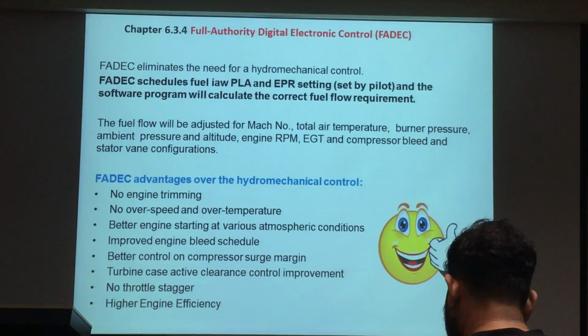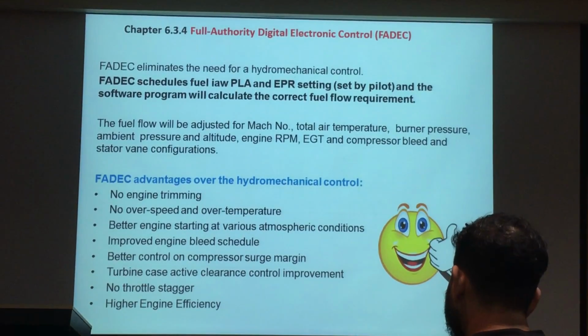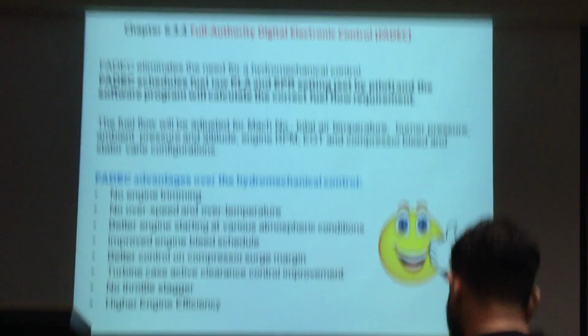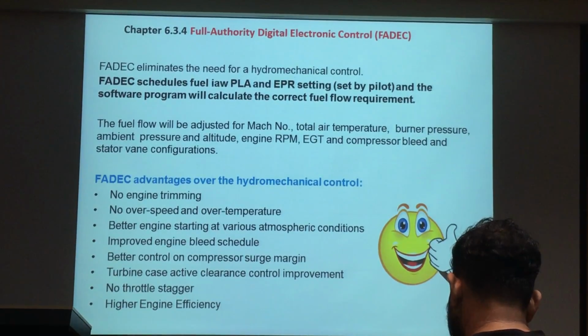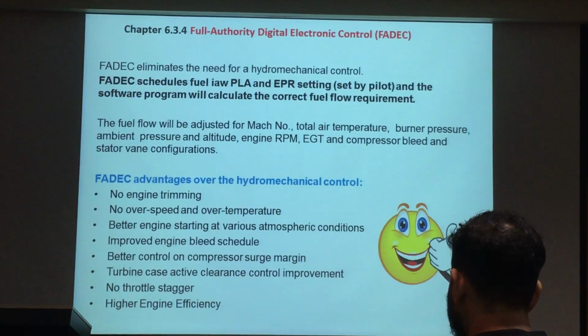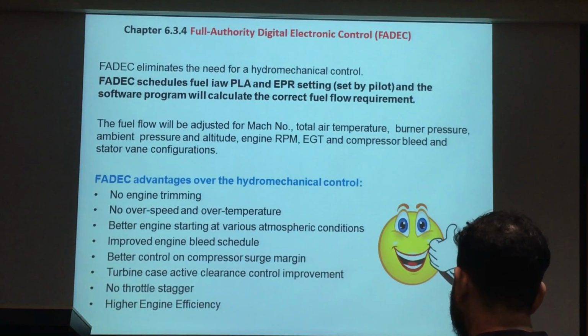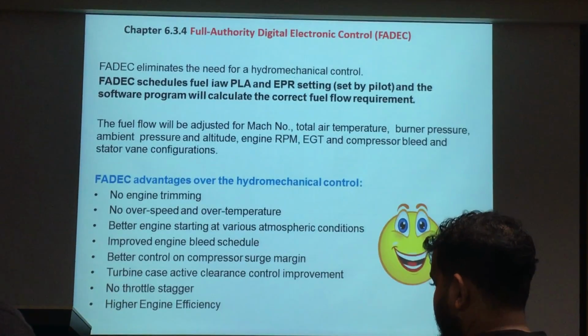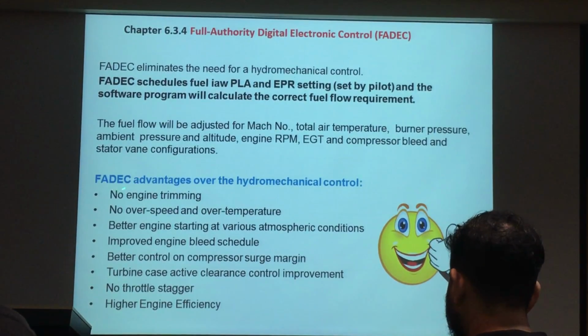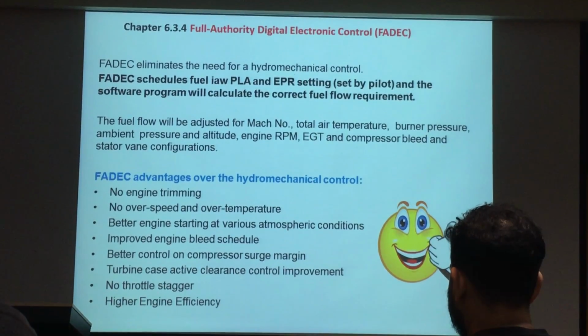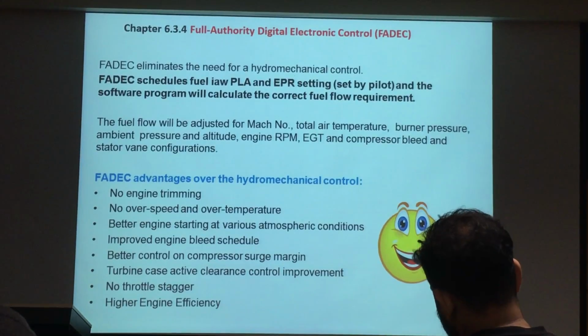Remember the FCU I mentioned to you? You only measure the four primary parameters. How about the secondary? It has secondary functions, correct? The secondary functions: remember your actuator movement, bleed valve control, bleed valve scheduling, stator vane configuration, vane scheduling. This is what you need. All controlled by your FCU secondary parameter function. So this is also done by FADEC. FADEC takes over the command.